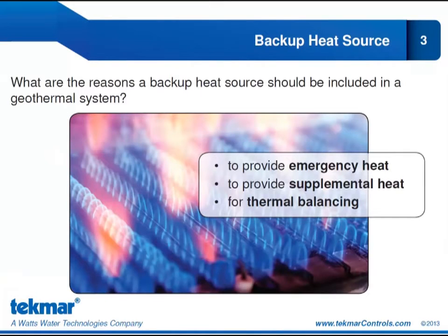So if we can choose a heat pump with a lower capacity and subsequently undersize our ground heat exchanger to provide maybe 70% of the peak load, then we need to consider having a backup heat source in our system to provide heat on those coldest of days.